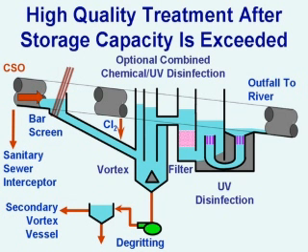This facility received a $20 million federal grant to test different kinds of technologies, including different kinds of disinfectants: chlorine with dechlorination, that's sodium hypochlorite with sodium bisulfite dechlorination, chlorine dioxide, peracetic acid, and bromine as BCDMH. So we've looked at a lot of different ways to disinfect the flow, and it included vortex separators, dissolved air flotation, chemical precipitation, and compressed media filter. And then, of course, UV disinfection.